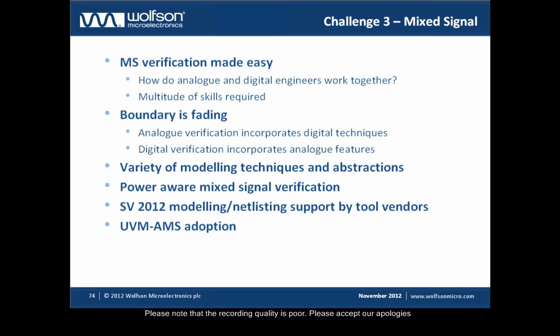Also, UVM-AMS allows us to adopt functional and metric-driven verification in the mixed signal space. So you add constrained random, you add cover groups and assertions, all with these real number models you have written in the first place, and plug that into a UVM-AMS testbench. And all of a sudden, you've got quite a digitally loaded test environment for your mixed signal chip.